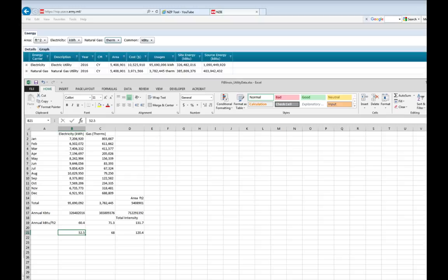We're looking at a meter that had last year's weather, and our building models are simulated with typical weather. And we don't want last year's weather to simulate. We want typical weather, so that when we predict, we don't predict an extreme high or an extreme low on the weather. We predict what's going to happen typically from year to year to year as we're looking at the planning aspect of these studies.